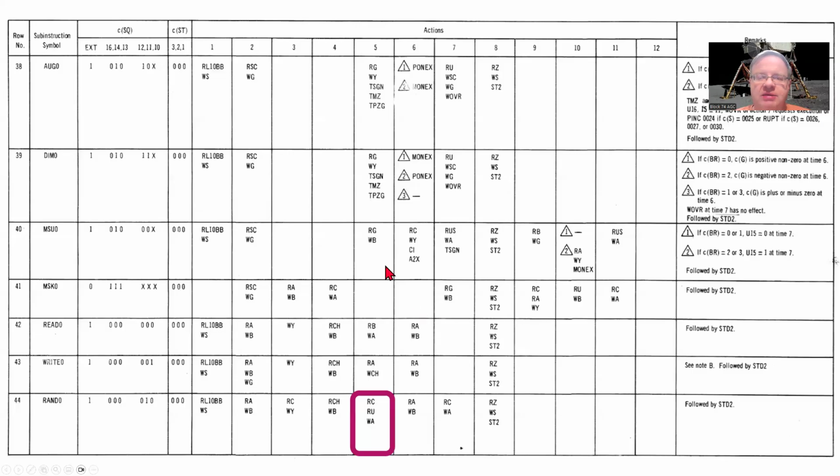When we start looking at the control pulses around the U register, or the summer, we'll notice some similar behavior to what we had to deal with on the A register. You can see here we've got both an RC and an RU simultaneously. If we just dealt with this normally, as we would with our octal transceivers, we'd potentially encounter bus contention. This is similar to what we had to deal with when we designed the A register, in that we can't read the contents of two registers onto the write lines simultaneously.